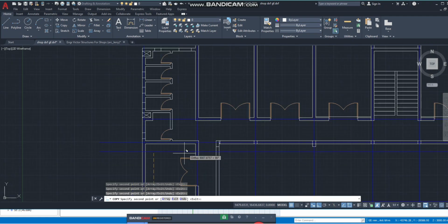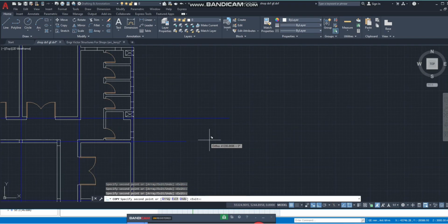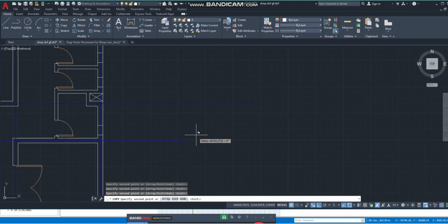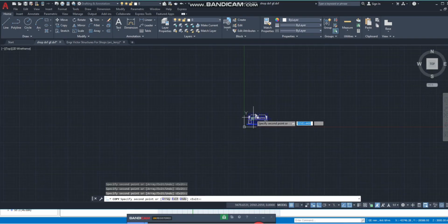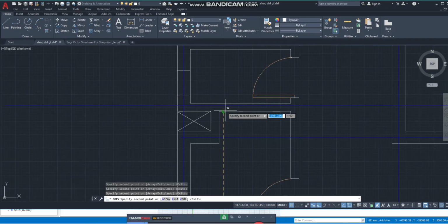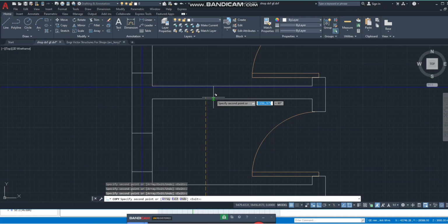So if you see in this case now, I'm dropping it away from following that exact point. It's not going at angle 90. So I will need to trim off this edge and make sure that my axial lines align. Because if your axial line does not align, when you take it as an external reference drawing to your design, you see that you have issues.